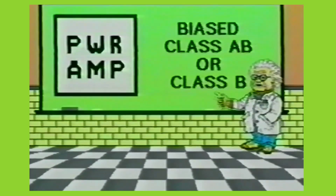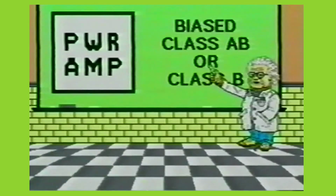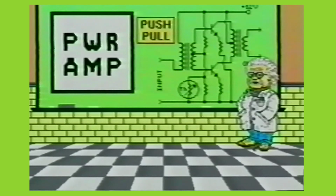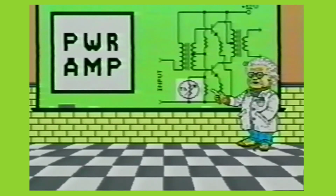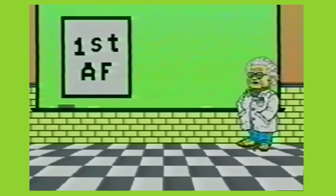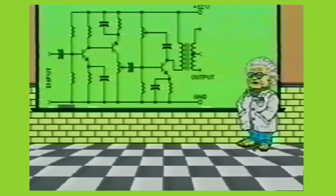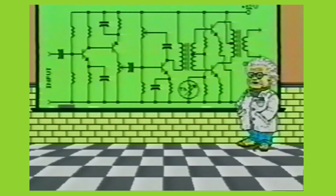The power amplifier stage operates in either a Class AB or Class B mode and uses a push-pull transistor configuration. A negative temperature coefficient resistor is mounted to both NPN power transistors to prevent thermal runaway of the stage. The output transformer properly matches stage impedance to the load impedance. As you will see, when the first audio frequency amplifier, the second audio frequency amplifier, and the power amplifier are joined together, the result is an audio frequency amplifier section capable of boosting the input signal to a considerable amplitude.